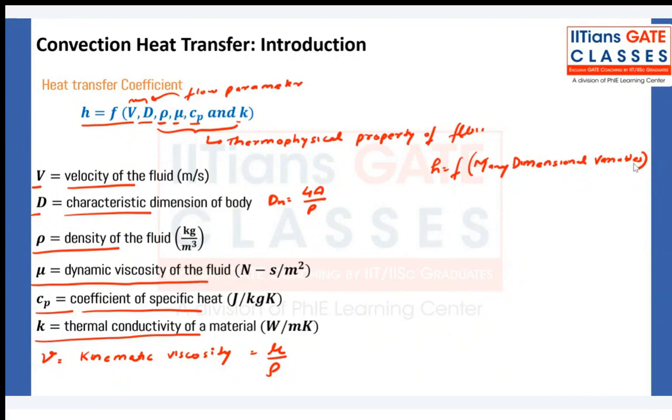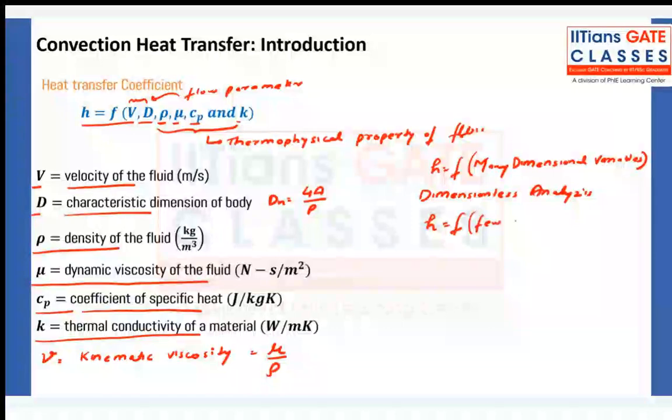And whenever one parameter changes, it is going to affect other parameters as well. So what to do? What we do is a dimensional analysis, dimensionless analysis, and we determine h as a function of very few dimensionless variables.